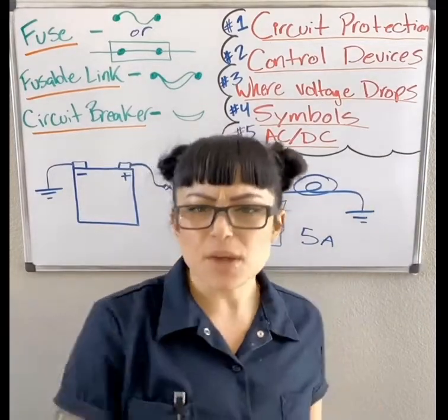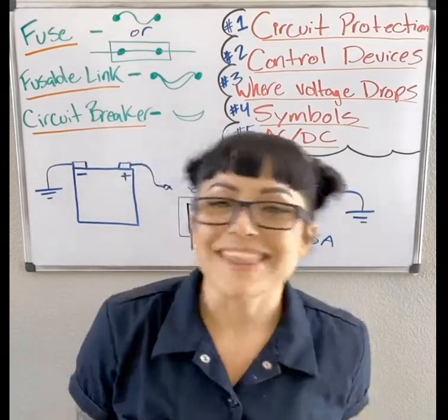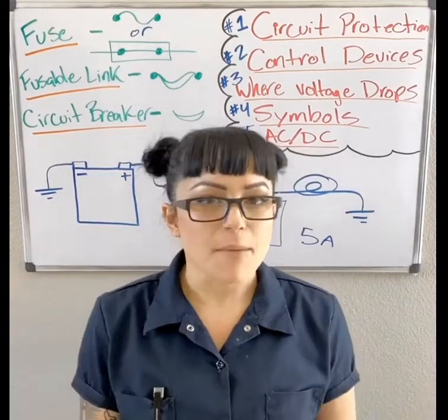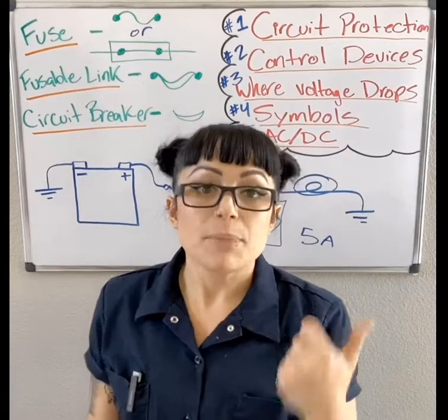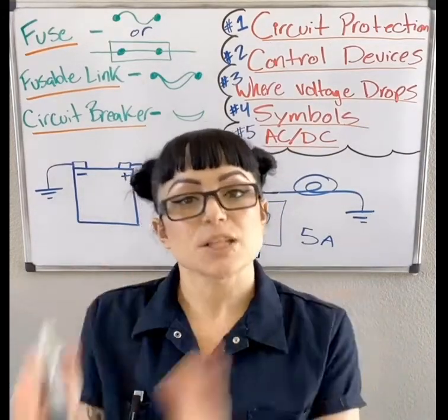And so if you keep putting in fuses and you're like, man, these crappy AutoZone fuses, sorry AutoZone, they just keep popping. They must be super bad. I'm going to go to O'Reilly. Guess what? You're probably going to pop those ones too, because the problem is not the fuse. The problem is the short circuit that is popping the fuse.